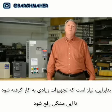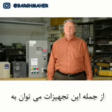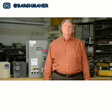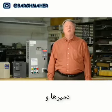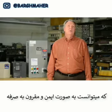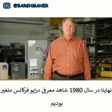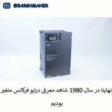So we've come up with many devices and inventions in order to compensate for that basic deficiency. Things such as belts and pulleys and sheaves. Things such as dampers and inlet guide vanes, eddy current couplings, fluid couplings, and so on, all to compensate for a motor that could only run at one speed. Well, it took us 100 years to come up with a device that could reliably and cost-effectively cause an AC motor to run at different speeds. Finally, in the 1980s, we saw the introduction of the variable frequency drive, or VFD.